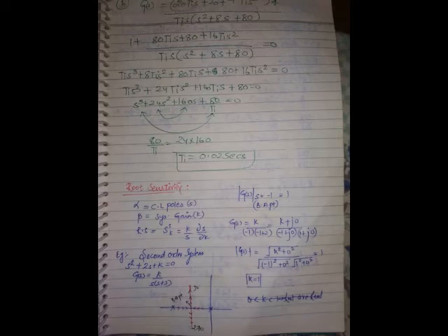Which one of the following is an advantage of a PD controller in terms of zeta and omega n? See here. Without derivative controller, this is omega n. With derivative controller, omega n remains the same. Omega n will remain fixed. Without derivative controller, this is zeta. By adding derivative controller, omega n will remain fixed, zeta will increase.